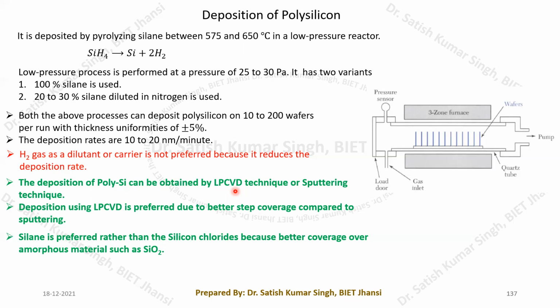Why is it preferred? Because it gives better step coverage. What does step coverage mean? That I will be explaining in the subsequent slide, so don't bother about it. You remember that generally LPCVD has better step coverage as compared to the sputtering technique, and therefore we generally use LPCVD.